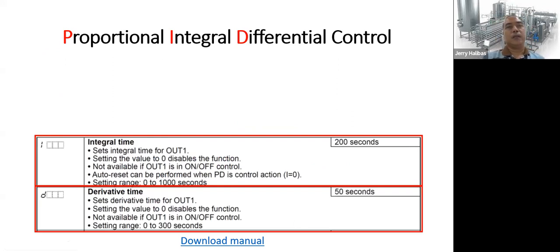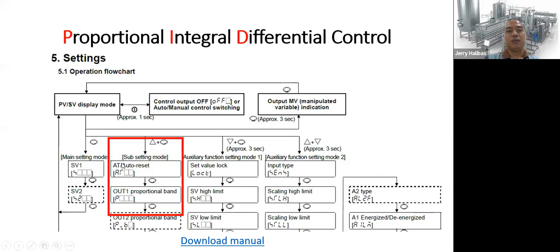We go back to one of the objectives of why we have to learn PID individually and in combination. It is not at all times that the system can be auto-tuned, because of mismatches in the system. For instance, instead of using a 1-inch control valve as the final control element, since it's not yet available, management decides to use the existing 2-inch valve. A 2-inch valve is too big for 1 inch.